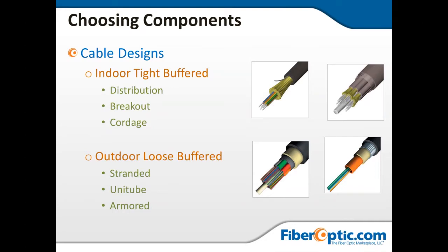Let's say if you have incoming ports on one side of a room and have to get cable over to the switches on the other side, let's say it's 100 feet. You wouldn't run, say, 72 individual fibers over. You'd run this particular breakout cable in between the points. So it gives you a nice coherent bundle. And when you break out, since generally they would serve as a long patch cord, then each one would in essence be a standalone 3mm patch cord, for instance.